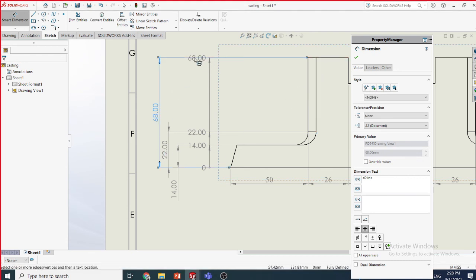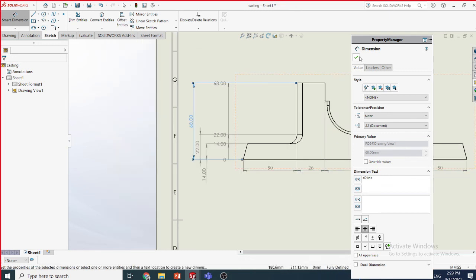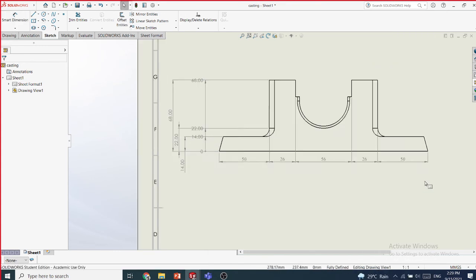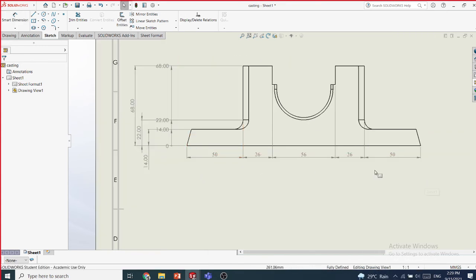Okay, so ordinate, we have a kind of a single arrow, and we are marking the references or the dimension areas from these other arrows. So starting with the dot here, we have a single direction arrow, and we mark 14, 22, 68, but here we have separate arrows, 14, 28, 68, same values at the end we are getting, but the representation is a little bit different.